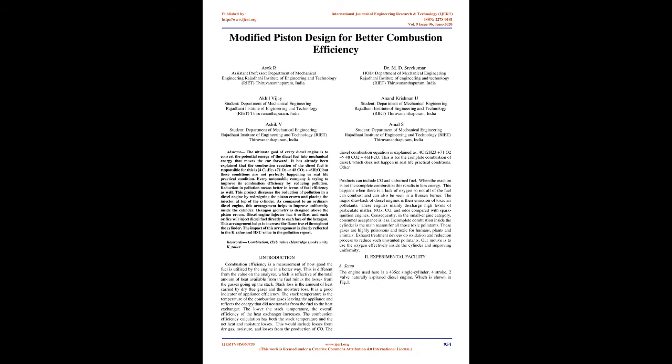Introduction. Combustion efficiency is a measurement of how well the fuel is utilized by the engine. This is different from the value on the analyzer, which is reflective of the total amount of heat available from the fuel minus the losses from the gases going up the stack. Stack loss is the amount of heat carried by dry flue gases and the moisture loss. It is a good indicator of appliance efficiency.